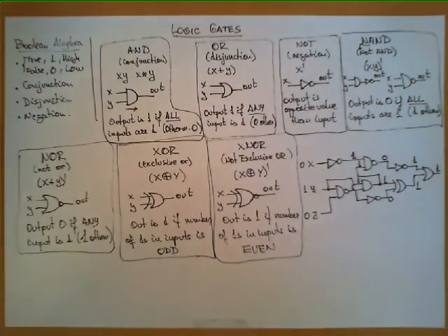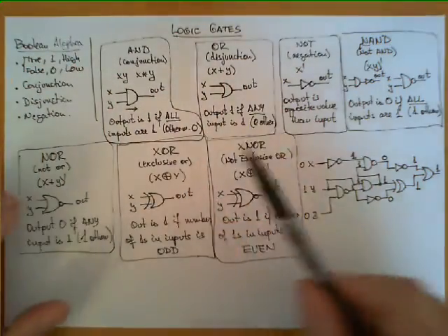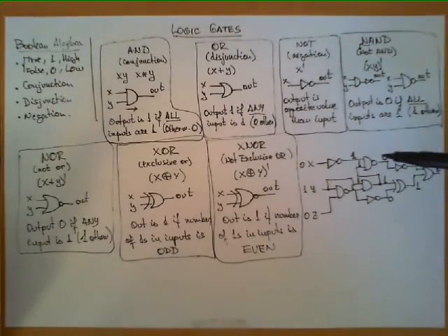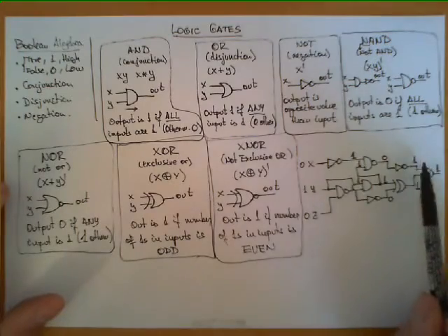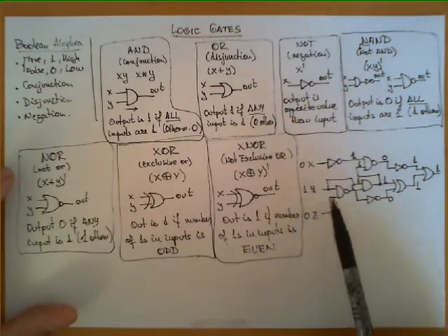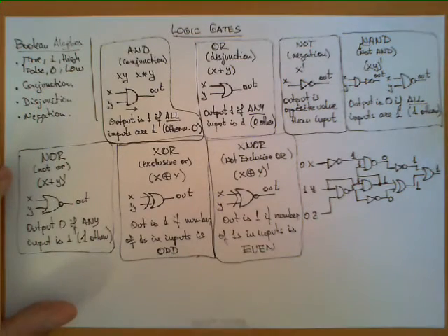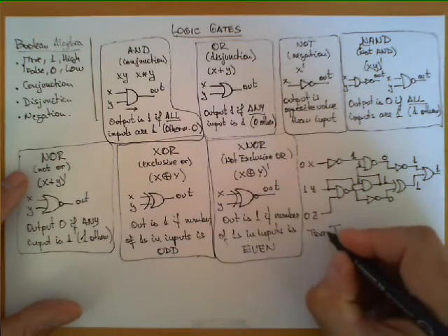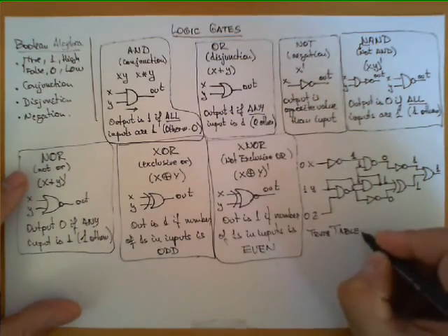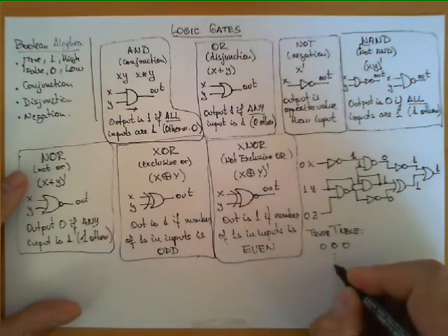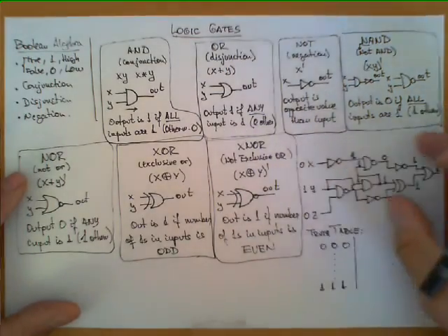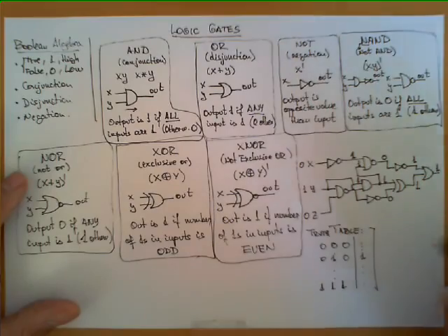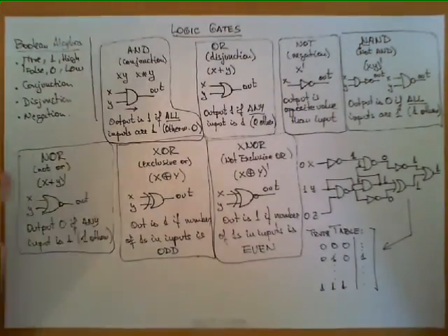So here we can see first how the logic gates are defined with their rules, how they can be connected, and with this connection we have something similar to a Boolean expression, because as we can see, and this is the connection between logic gates and Boolean algebra, we have here a function that receives 3 possible symbols, each one taking values 0 or 1, and produces an output. And of course, in order to derive the truth table from this circuit, we can try all possible combinations in x, y, and z from 0, 0, 0 to 1, 1, 1. We apply these rules the same way we did for the 0, 1, 0 combination, but we can obtain the rest of the values and very easily derive the truth table from the circuit that is made out of logic gates.